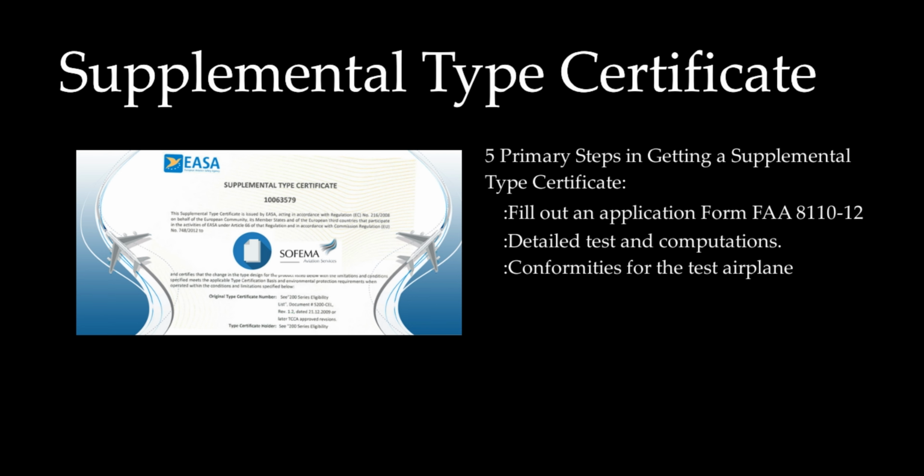Then you must conduct conformity inspections of each part and installation, which verifies to the FAA that the modification conforms to the design data. The FAA Manufacturing Inspection District Office, MIDO, or a designee, must verify that each part and installation is accurate and complete, and that you have complied with applicable regulations and airworthiness standards.